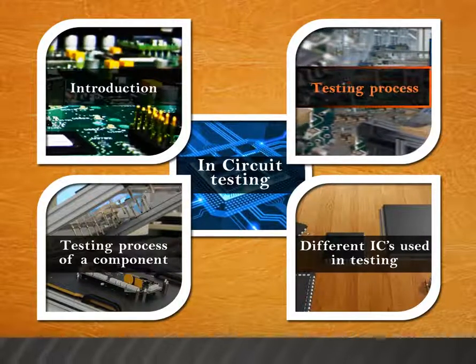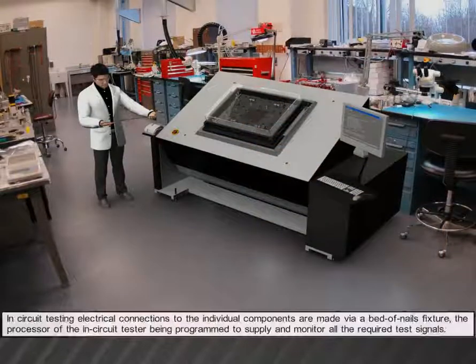Testing process. In circuit testing, electrical connections to the individual components are made via a bed of nails fixture, the processor of the in-circuit tester being programmed to supply and monitor all the required test signals.